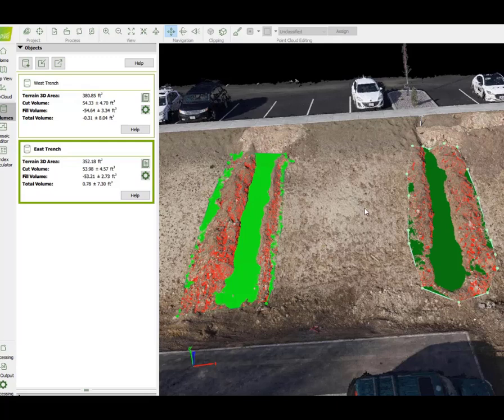So I think that is one of the takeaways, that if you want an accurate volume, you don't necessarily have to pull out your GNSS receivers or total station and establish 3D GCPs. You might be able to just go to a site quickly and easily, put out some scale constraints, obtain imagery in minutes, and obtain accurate volumes. So another tool in our toolkit there.